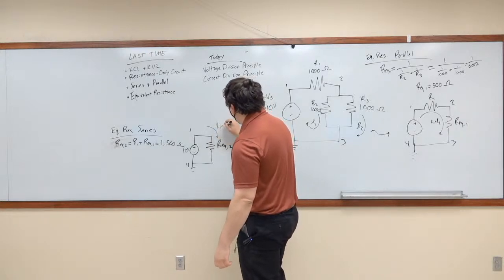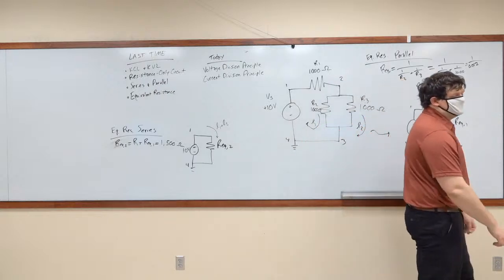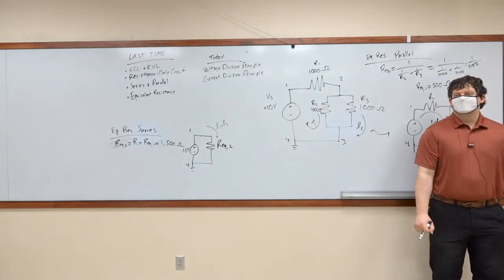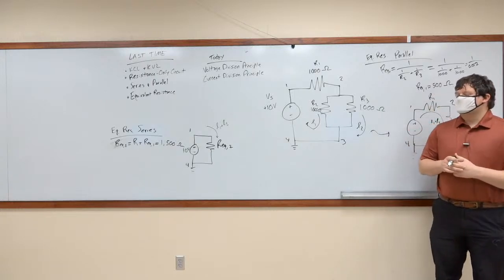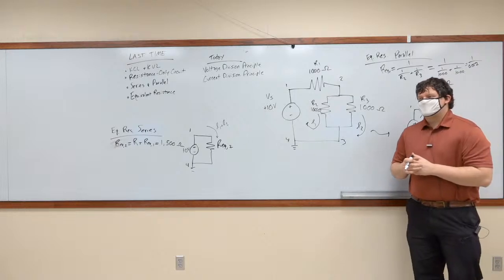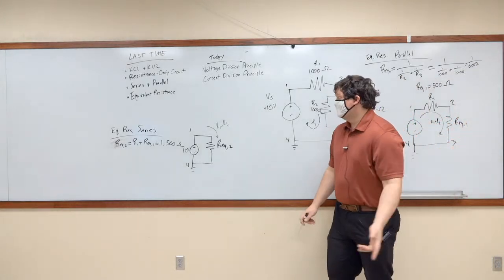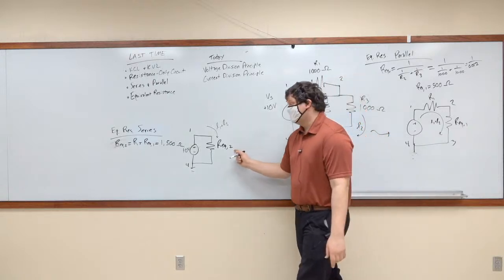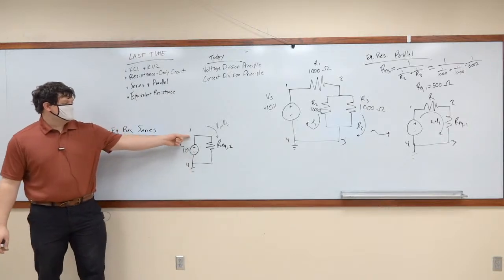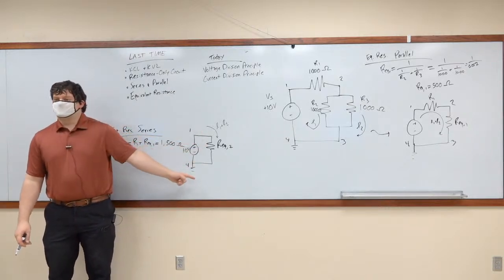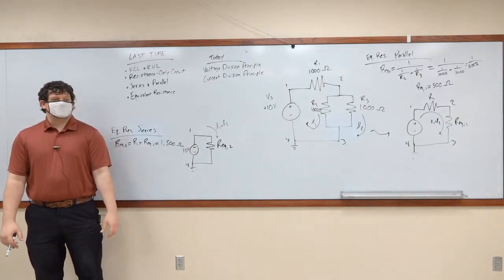This is still L1 plus L2. How much current is leaving that battery? How do we even calculate that? We use Ohm's law on REQ2, right? Because we know what the resistance of REQ2 is, and we know what the voltage is across REQ2. So all we have to do is just calculate the current through it.